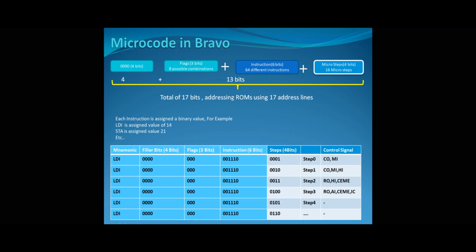However, those flash memory chips that we talked about are 128K, right? So in order to address those, we normally need 17 bits or 17 pins.